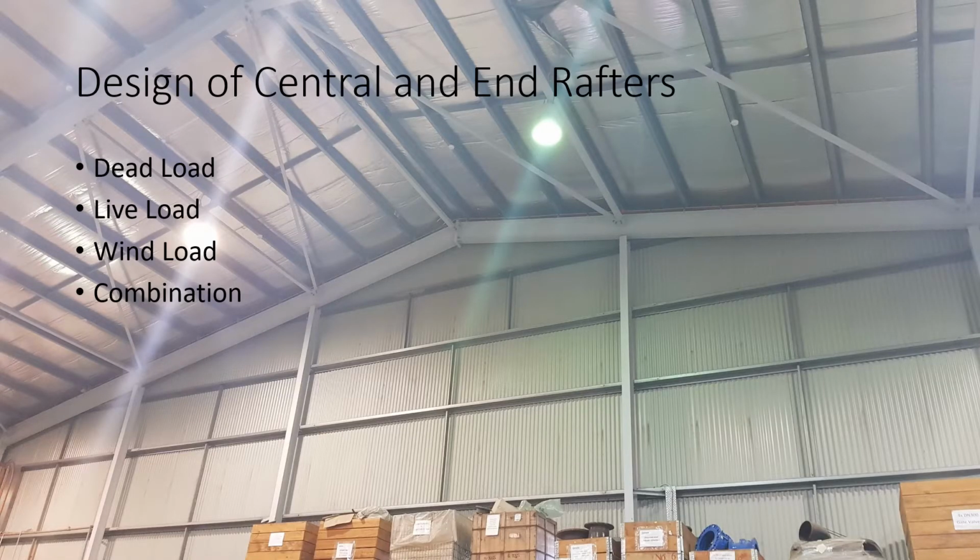Design of the central and end rafters. Calculation of the dead load, live load, and wind loads, and then the total combination of all three was combined. Design capacity tables were then used to choose a suitable member. For the central rafter, we chose a 460 UB 67.1, and the end rafters were a 360 UB 44.7.